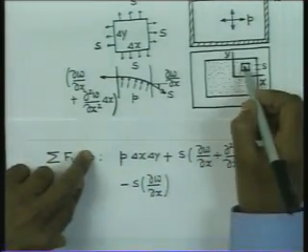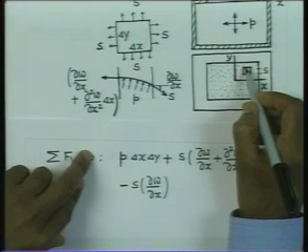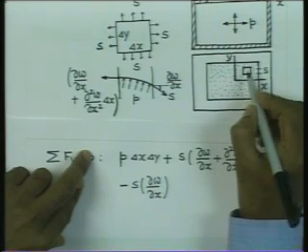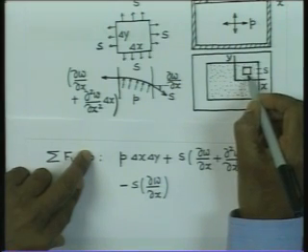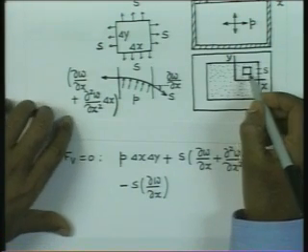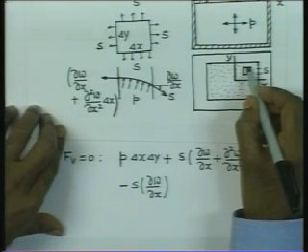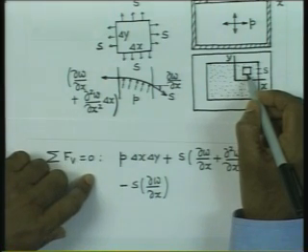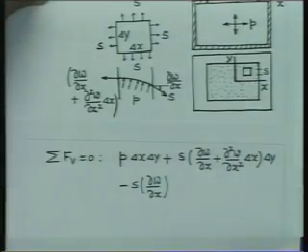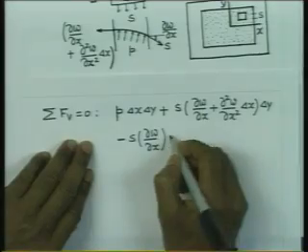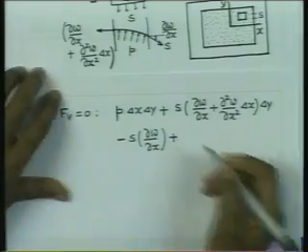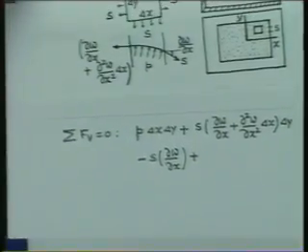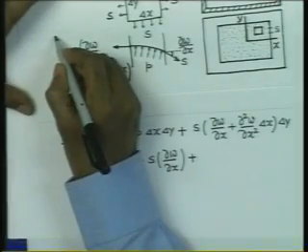Similarly, if we consider the other side, here we will have some forces coming due to tension per unit length, and here this will also be acting. So, if we consider that the slope here is ∂w/∂y, and the slope here is ∂w/∂y plus ∂²w/∂y² into delta y, then we can write from the other side, S. If you would like to draw a sketch for it, we can do it that way.